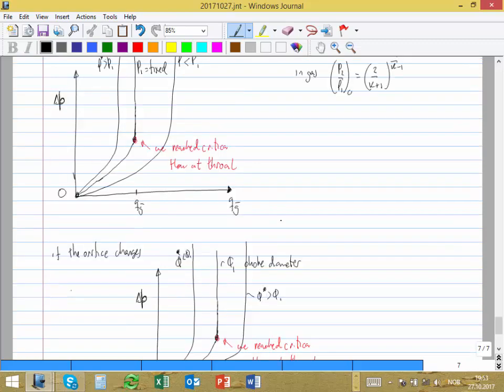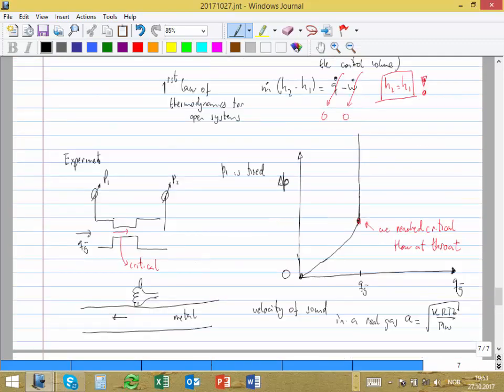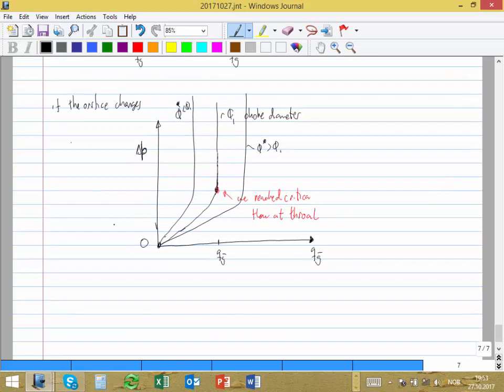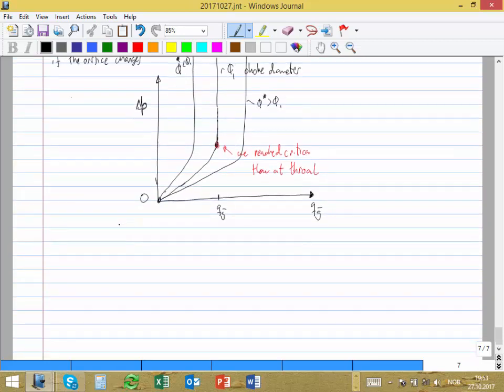So that curve was for a fixed opening and for a fixed pressure, but when we have to select the choke, it's very important which choke to use. So I want to spend some time going through the development of the choke equation, because most of the choke models available in the literature are based on the same concept, the same idea. I'm going to do it first for liquid, just to show you something interesting, and then for gas, and that's going to take some time. I think up to the end of the class, but let's see. So, choke equation for liquid first.